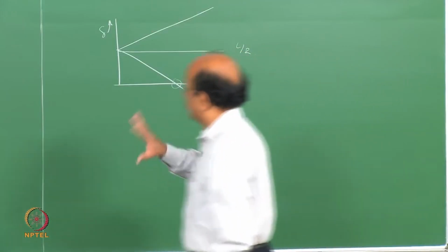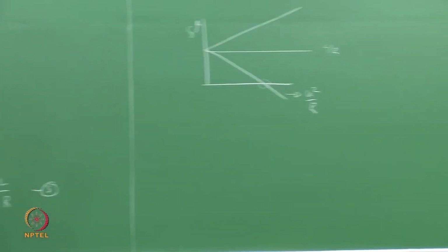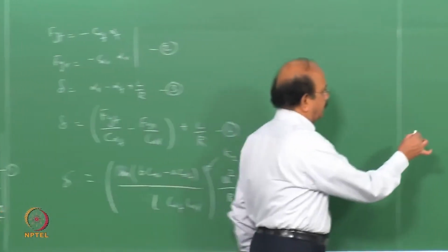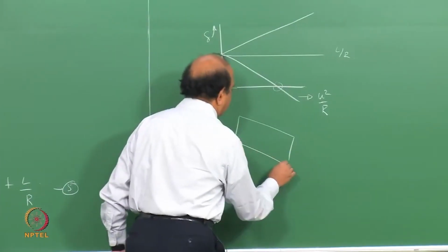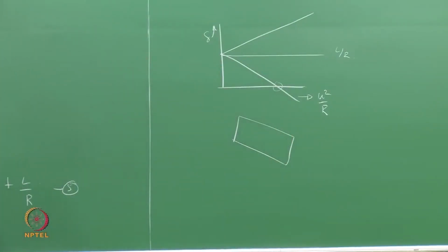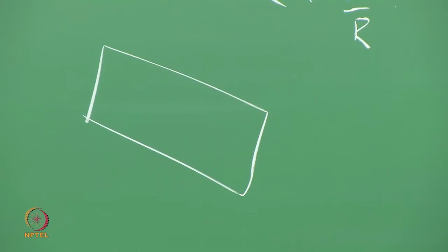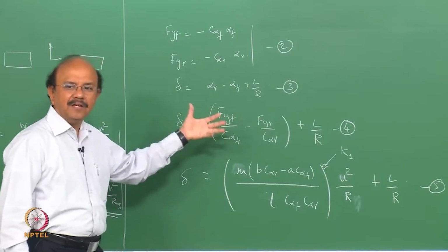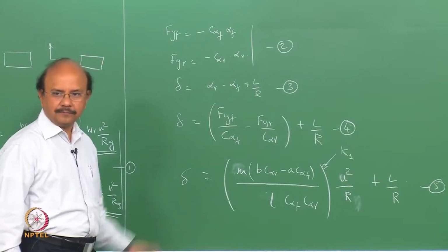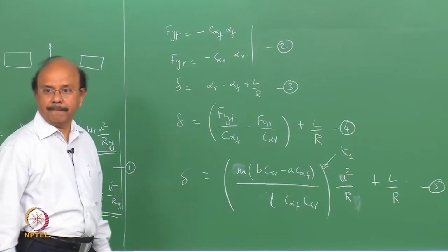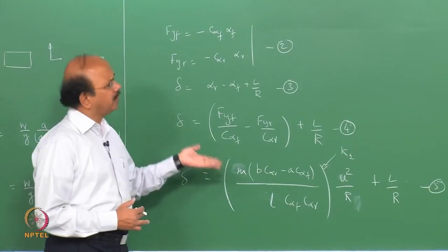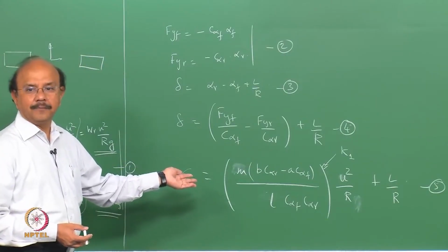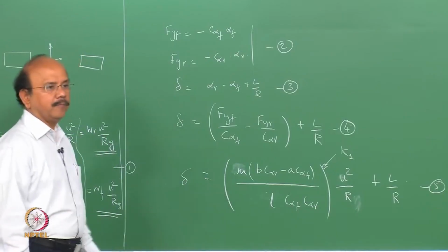First, let this get into our mind. Is this clear? Okay. Why is this happening? Let's go to my front tire. Let me put that front tire. Now, actually, it is this alpha F and alpha R which is playing the role of cornering. Those two are very important. That's why the tire is very, very important. Look at that. The tire plays such an important role in this whole handling characteristics.